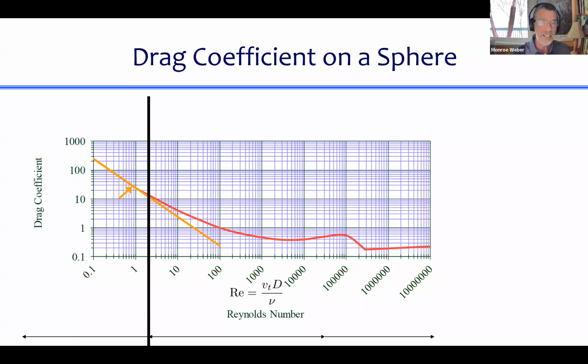And what's going to save us here is that most of our world with removing particles in water treatment processes is small enough and slow enough that it's all in the laminar range. And so we can use that laminar range where it's just a straight line on a log-log plot. And we can use Stokes' law.